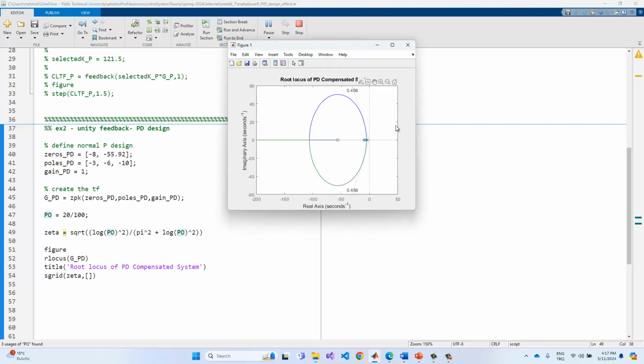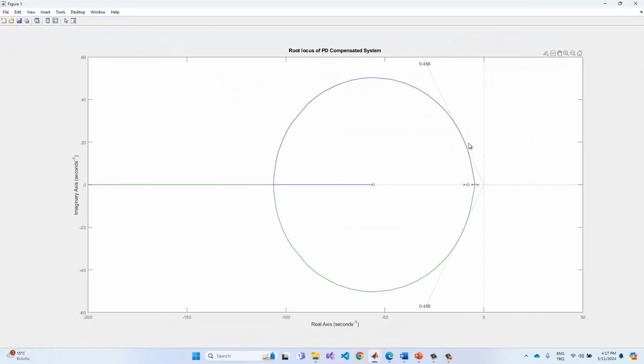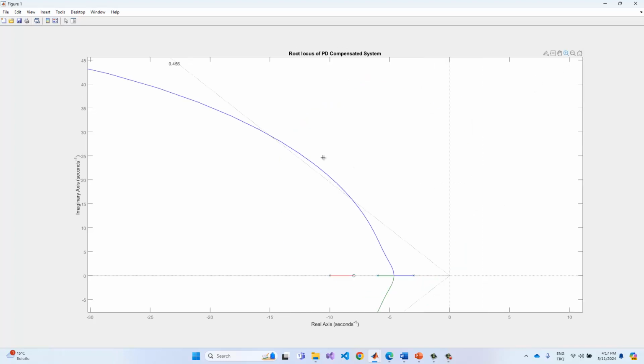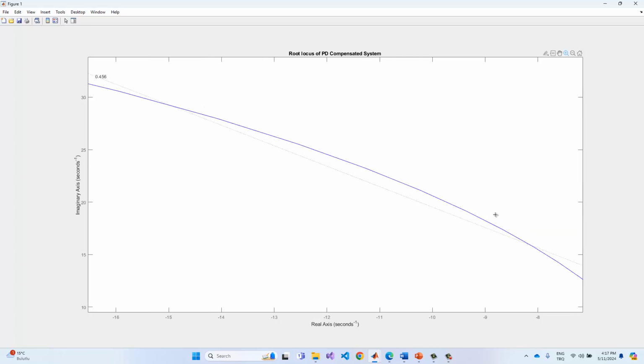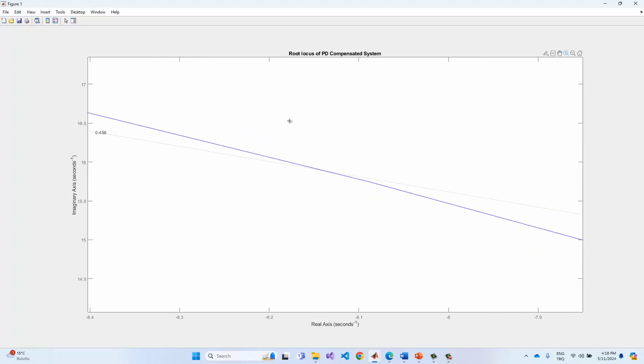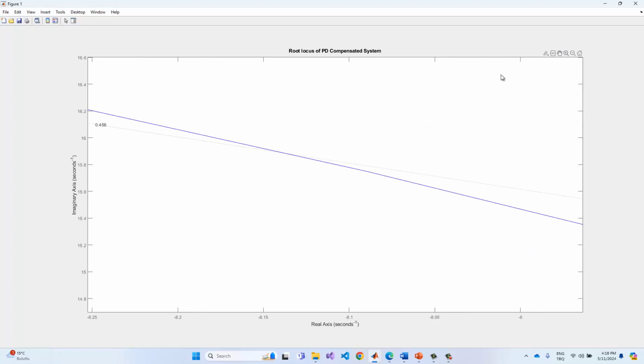And so if I run this code, then we will have this for the PD selection in here. So we have the 2 points in here, just like this one. For example, we can select these terms in here, and then the intersection point must be selected in here. 5.34. It's the overshoot in here, and just see that the dominant poles of this term are minus 8.14 plus 15.9. This satisfies the condition.